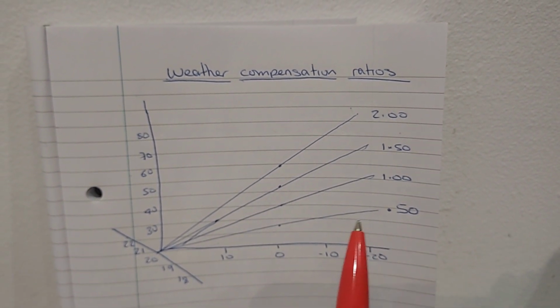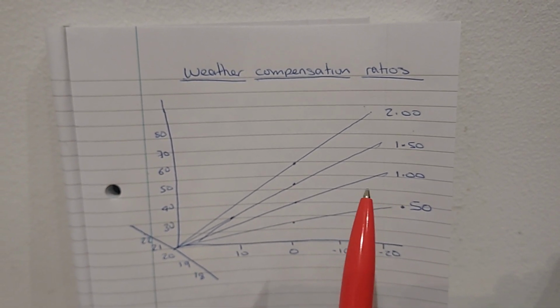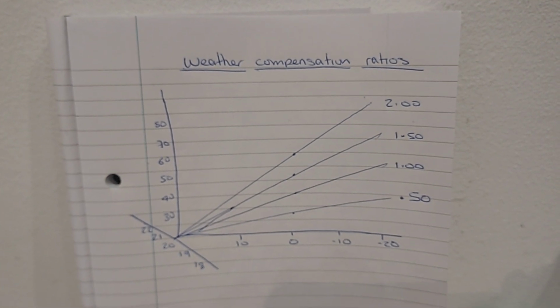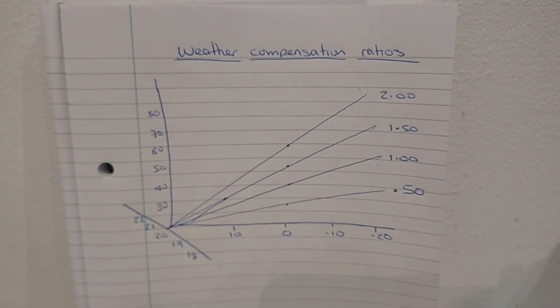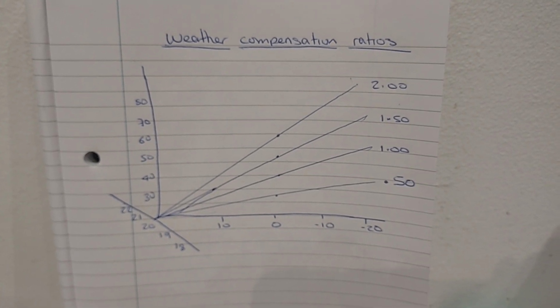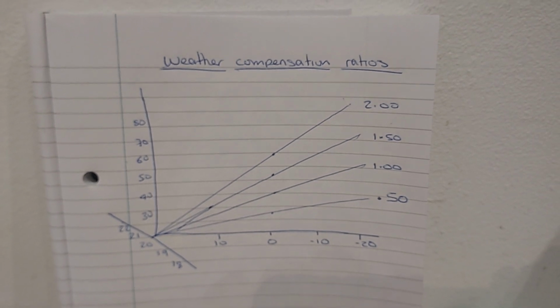And this is when I would be using mixers. I'd be having my underfloor down here somewhere and my radiators down here somewhere, and using variable temperature mixers on there and keeping those floors cooler. Now that would also give us a better comfort level, I believe, in the property if we did that.